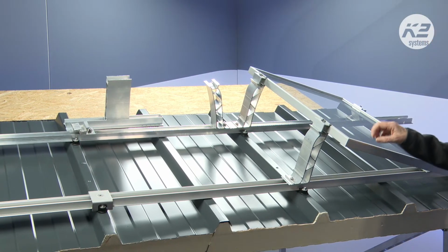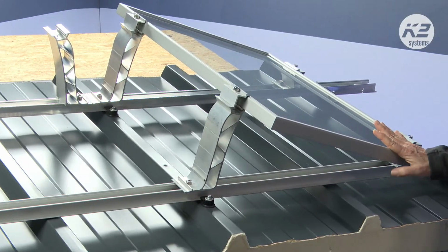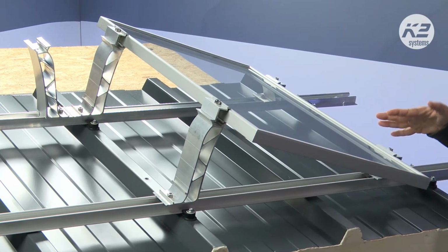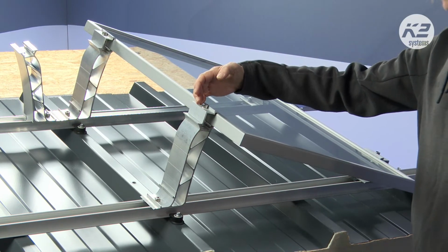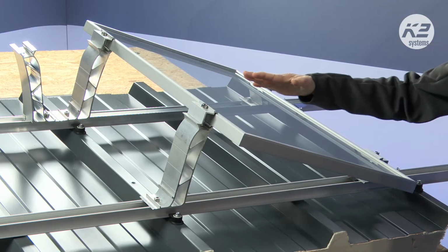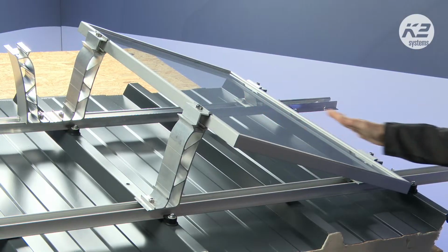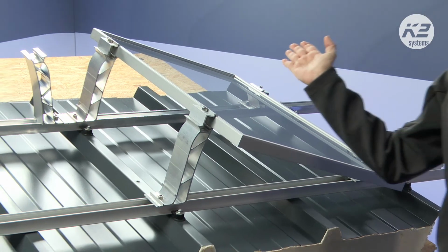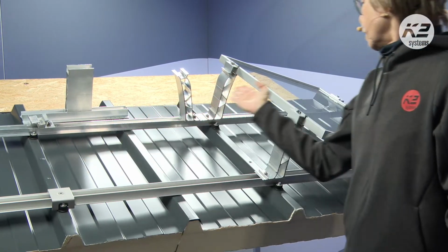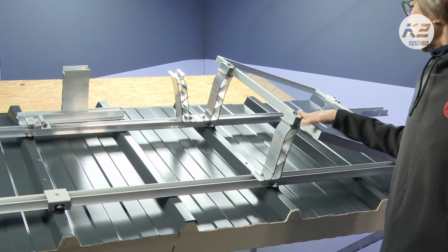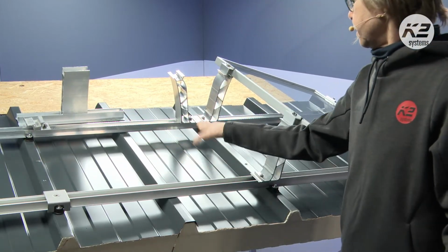So there we have the first type of inclination system on trapezoidal sheet, that is Dome 6.10. That means with 10 degrees inclination. You can create it as an S-Dome, that means S for single, in one single direction. Or you can also plan it as a D-Dome, that is an east-west system. That means the second inclination is in that direction, and it goes always like this.